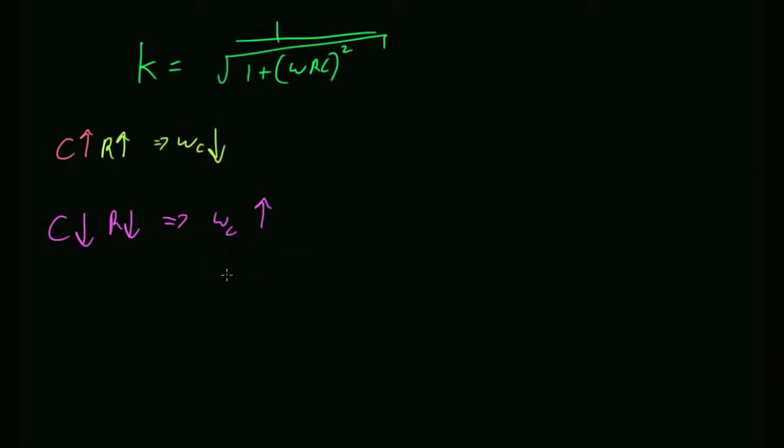On Monday, we will learn how, instead of going by trial and error, if I say, build me a filter with a cutoff frequency at this many hertz, you could pick the resistor and capacitor values to get exactly the cutoff frequency you want. But at the very least we can agree that it is your choice of resistor and capacitor value that sets your cutoff frequency.